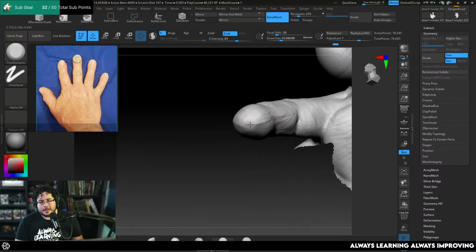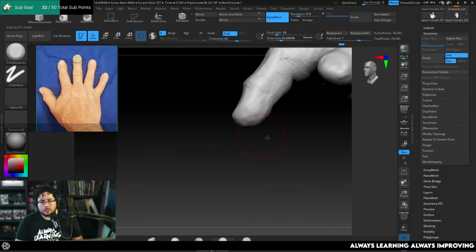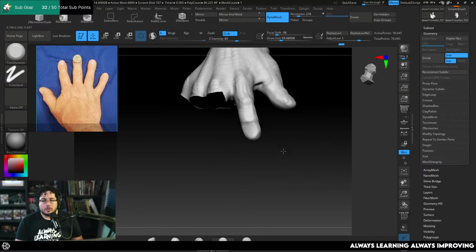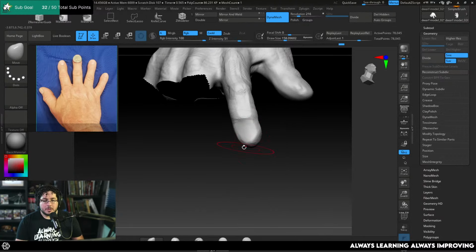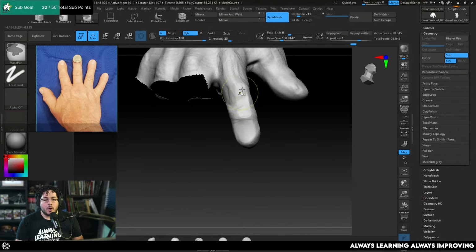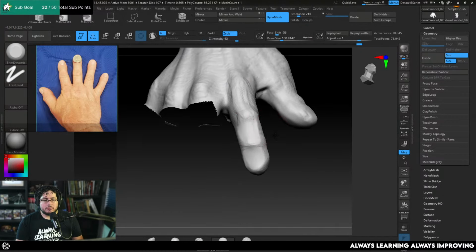But for us in 3D, what's important is that the normal maps that we normally export for our objects will look different depending on if they're for OpenGL or DirectX. It's very easy to convert. You just flip the green channel. So if you invert the channel, it's just gonna work.